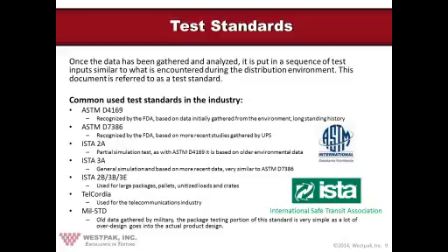There's no simple, easy answers. Like you don't say, okay, do an ISTA 2A or ISTA test if you have this product, and do an ASTM test if you have this other product. They're two different organizations essentially doing the same thing. They both consist of tests that we're going to talk about in a minute, which is a series of drop, compression, vibration. For example, ISTA 3A and ASTM D7386 are based on the same essential study done by UPS. They started co-developing the standard together, and then towards the end they went their separate ways. But if you look at the two standards, they're very similar. So it's just a matter of what your preference is.